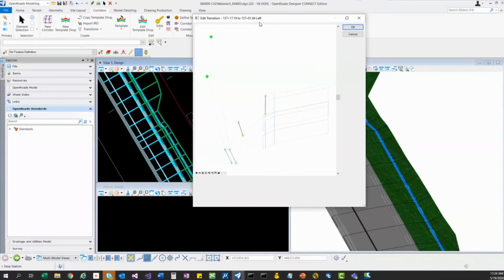What comes up now is it already found a bunch of points to connect to. So you'll see here's the first part of your end condition, that first range, and your second range. So you kind of see them next to each other. And what you can do is tell what points go to what points. This one up here didn't connect, so you can just draw those together like that. That's saying, okay, take this point to this point, right?